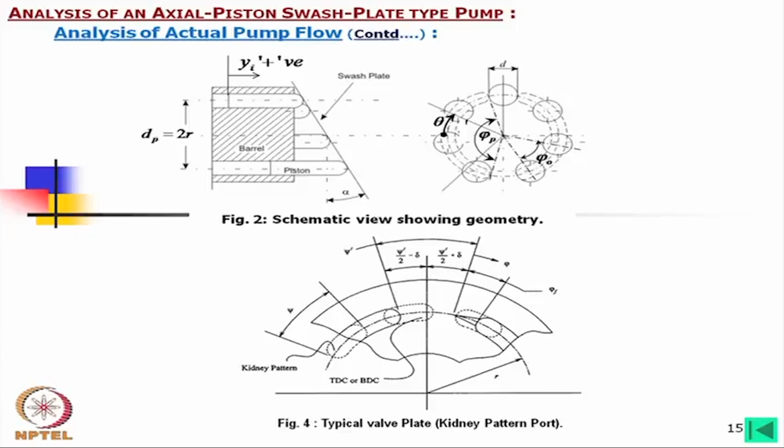Whereas if you provide this silencing groove, this pulsation in the pressure will be controllable, as well as there will be less noise. So that is why the name of this groove is the silencing groove. It is actually controlling the pressure pulsation, which reduces the noise.